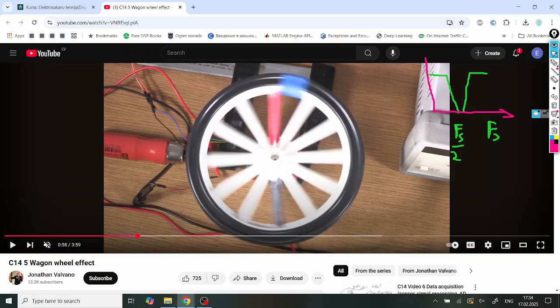What happened here is that we actually increased the speed at which our wheel rotates all the way from 0 up to F sampling by half. So that was this point, F sampling by half, when it was rotating. If we were not making it slow mode, you would notice that it was the fastest effect visually. Now at this point it has changed direction and will start to decrease rotation speed all the way up to stopping completely at sampling frequency.